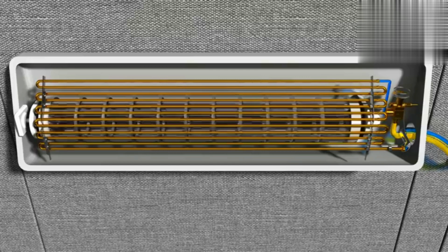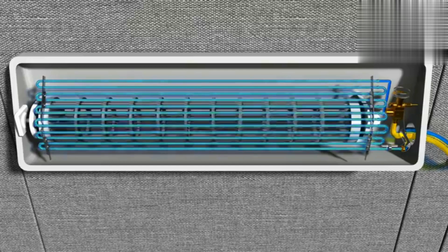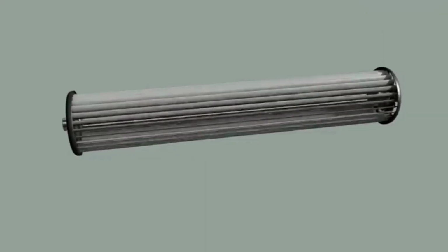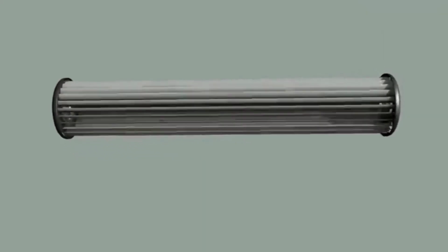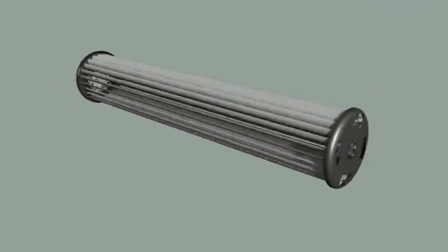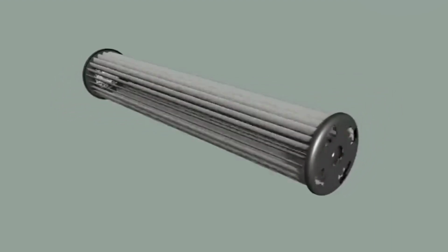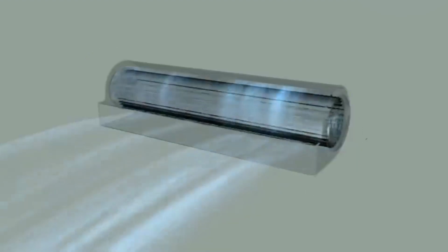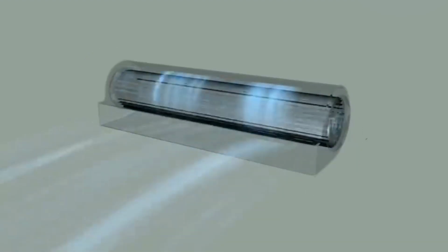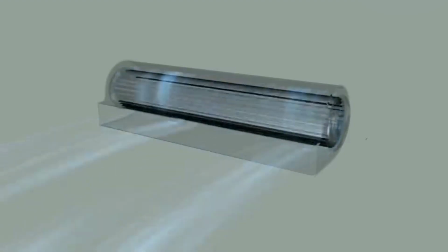A refrigerant passes through the pipes of an evaporator and takes away heat in this process. As the fan underneath starts to operate, warm air in the room is sent to the evaporator and cooled air is emitted. Fans used in the indoor unit of an air conditioner are shaped as a cylinder rather than the more familiar propeller. Such a type of fan is called an impeller. As wall-mounted air conditioners cannot take up large space, an impeller type of fan is used instead of a propeller type.